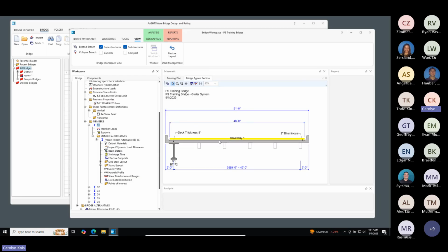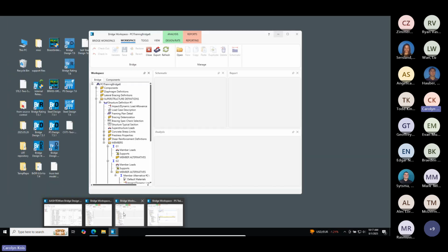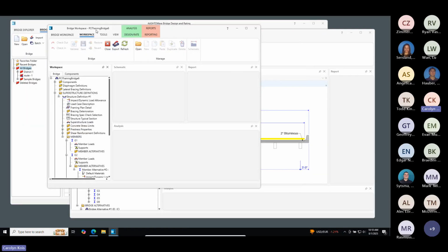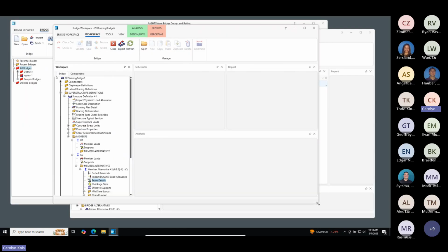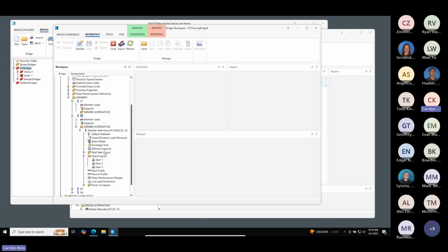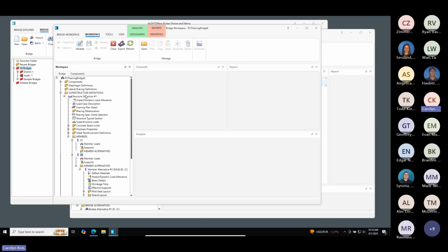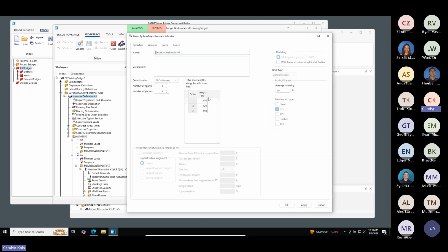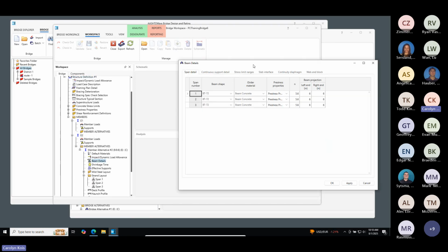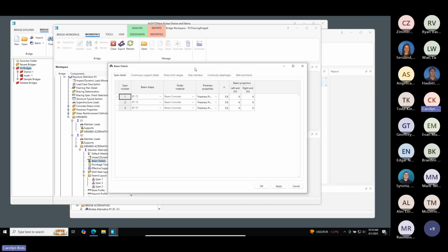The one other thing I want to mention that's not in this example is if we have a bridge like this. This is a similar bridge, but it is multi-span and it's made continuous. It's simple span for dead load and it's made multi-span continuous for live load. For this type of bridge, with multiple spans within the same structure definition, when you go to this beam details tab, you are going to see a couple of other things that we don't see for the simple span.